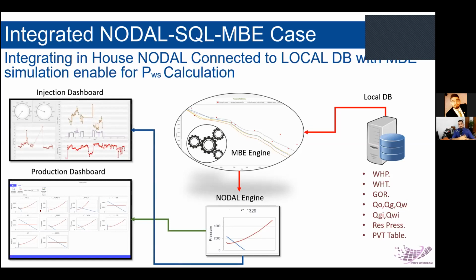This is also done by altering the reservoir pressure, because injection wells are very sensitive to reservoir pressure. You should not keep your reservoir pressure fixed whenever you are monitoring an injection well. This is not an accurate thing to do, because you will think there is a specific thing happening inside the reservoir, and actually you will come to find out it's quite the opposite.